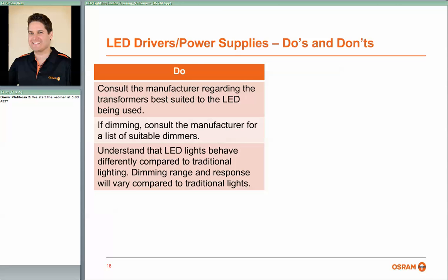Another question that's been asked is about flickering without dimmers. So going back a step, again, depending on what product we've got, flickering without dimmers could be an issue with transformers and compatibility. If you're not meeting the minimum load, the transformer may be trying to start the lamp up, but it's not enough to sustain the light source being on, and then it will switch off and continue cycling through and either flicker or not work at all. So a couple of things that could help there is either changing the transformer to one that's compatible, or potentially putting on more lamps to add load to that transformer, for example.